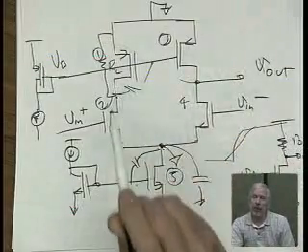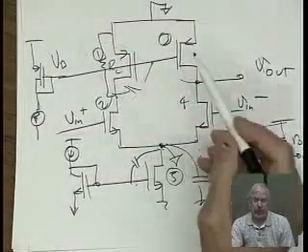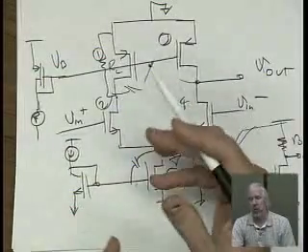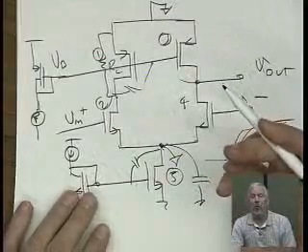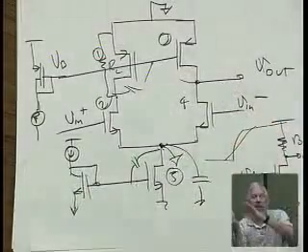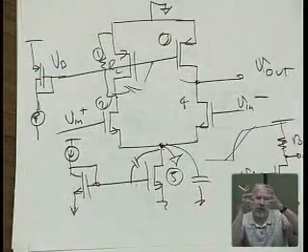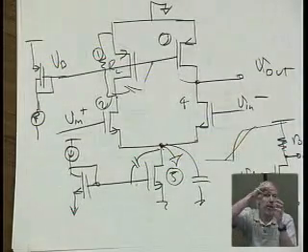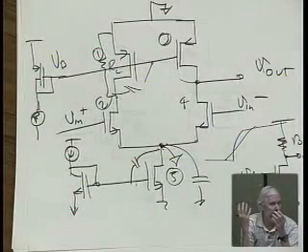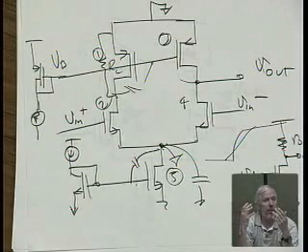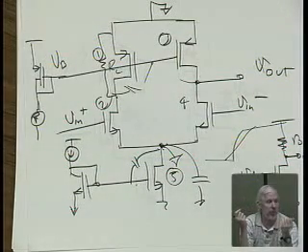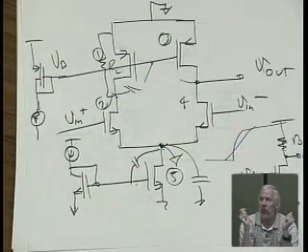Where this becomes really important, where do we have important poles being created that are different? Think about our folded cascode circuit, right? When you fold that thing over, you've got a bunch of extra nodes sitting inside where that folding's happening. That's different on the two sides, so you get a fairly complex pole and zero combination going on there, the high order poles and zeros.